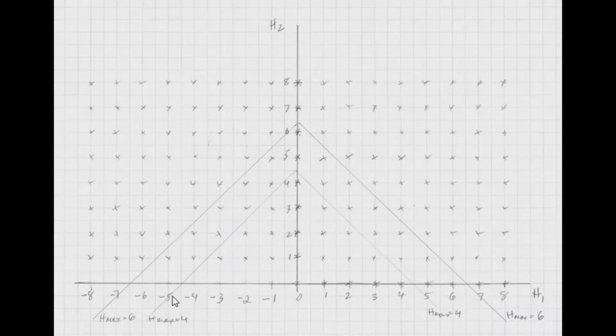Everything below it would be included, but nothing above that. So that way you can make the problem a little smaller by throwing away harmonics that you don't need. This is less of an issue in many kinds of circuits like LNAs and that sort of thing. It's much more of an issue in mixers, and we'll talk about it with regard to mixers in one of the subsequent videos.